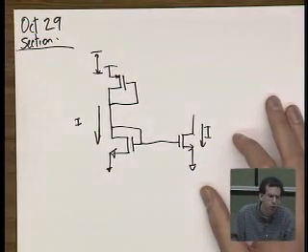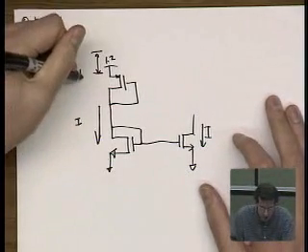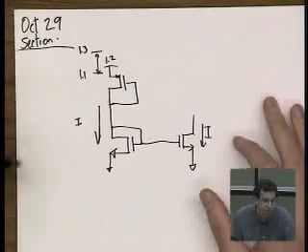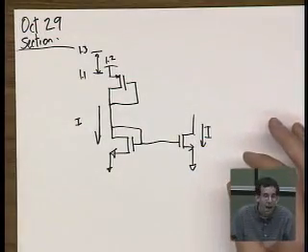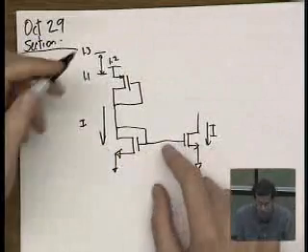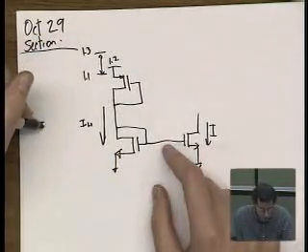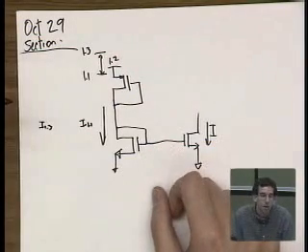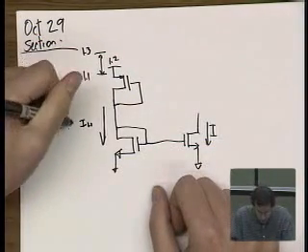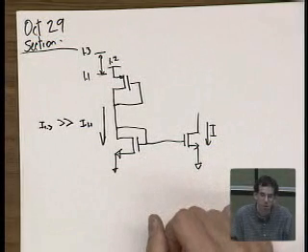I forget, Saurabh made the project, so I don't know the exact specs, but let's say it's nominally 1.2 volts. It might be 1.1 to 1.3, okay? So if you look at this master bias generating structure, I at 1.1 versus I at 1.3, the current is very sensitive to supply. So the current with a 1.3 volt supply is going to be a lot bigger than the current with a 1.1 volt supply.